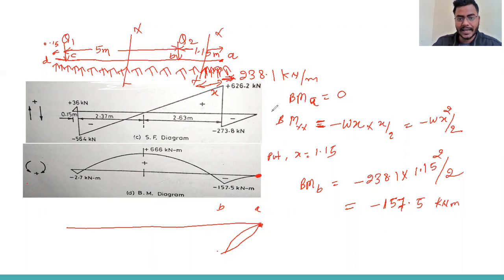So this is the general expression for bending moment. This is a mathematical section, but I am going to discuss it because we need it. If you don't have any idea about that, you can get some idea from this. So bending moment, the general expression is minus W x square divided by 2. Differentiate the bending moment with respect to x, you will get minus W x.